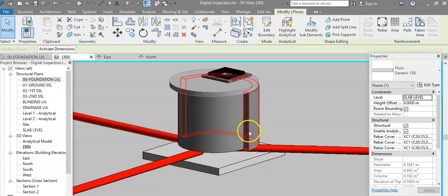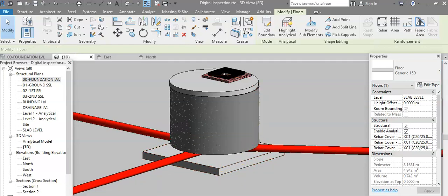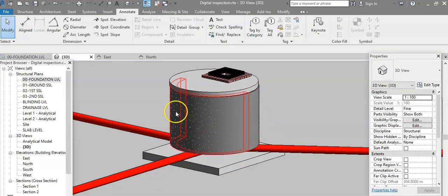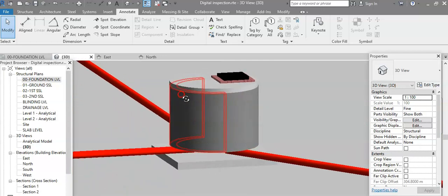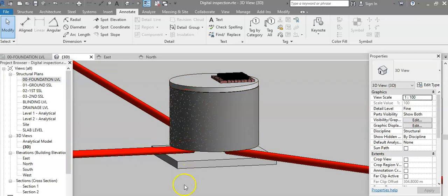We are left with one item here. If we go to this, they call it the concrete surround. What is the concrete surround? Concrete surround, to protect the manhole ring, is concrete in situ, similar to the concrete we had for the manhole base, but this is poured at the end of the construction around the manhole ring to protect it. And as you see, now we can tell why the cover slab is bigger than the manhole ring, because in the end it is tied to it with the protection.